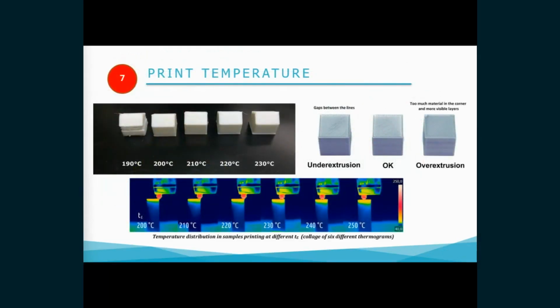Temperature is extremely important for making a high fidelity print with a 3D printer. The chemical makeup of a thermoplastic directly influences its glass transition temperature, the temperature at which the filament turns from a brittle filament into a rubbery substance that can be extruded.